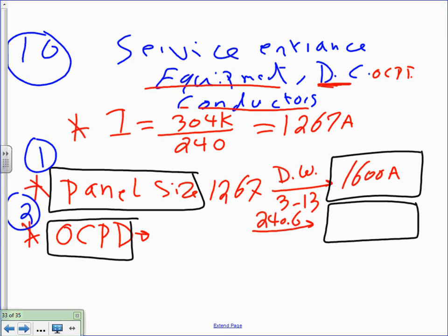That's when it becomes goofy to use single phase for this size. That's why 3-phase becomes a big deal. It's not a good idea to get into thousands of amps single phase. Too much on the feeder single phase, too much unbalance. So that's why they feed them with 3-phase.